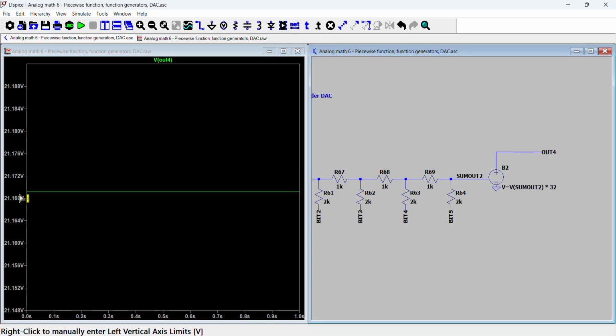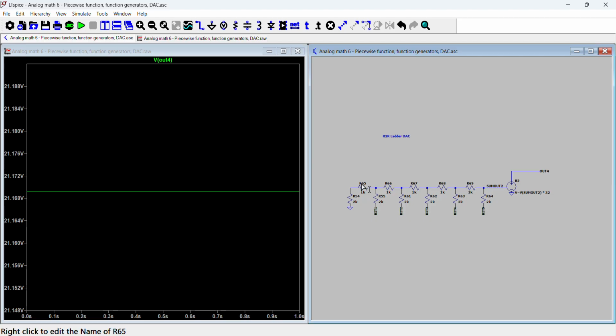And I do. So it's a little bit over 21, so it's not super accurate, and I'll talk about why. But you can see the manufacturability of this is much better because the R2R ladder essentially is you put a resistance in parallel with this main ladder that is 2 times the resistance of the resistors in series. So over here, all these resistors are 1K, and then you have these resistors 2K pointing down towards the inputs, and then the last resistor has to be grounded.